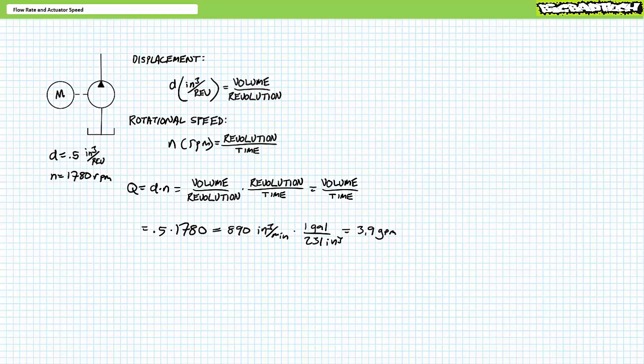Another simple method can be used to vary flow rate even for fixed displacement pumps. All you've got to do is just drive them faster or slower to meet flow requirements. Increased rotational speed means more flow rate at a given displacement. In contrast, decreased rotational speed means less flow rate at a given displacement. In much later lectures, we'll examine a power electronics device known as an inverter that can vary the output voltage magnitude and frequency to a motor under its direction, thus changing the motor prime mover and the pump's driven speed